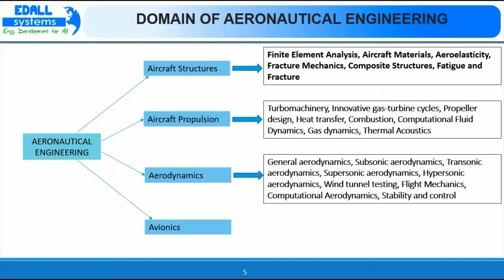Then we have transonic aerodynamics. Transonic aerodynamics is the study of when the aircraft reaches nearly Mach 1. Then it is supersonic aerodynamics, where the aircraft is moving at Mach numbers higher than 1. That is very complex, as shock waves and everything are involved. Hypersonic goes even further than that. When the aircraft crosses Mach 5, it goes into the hypersonic region. The study of these regions comes under hypersonic aerodynamics.